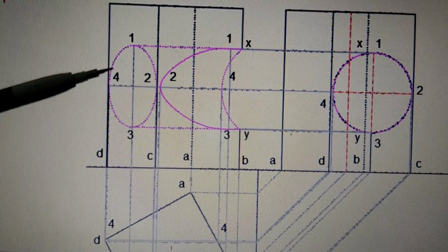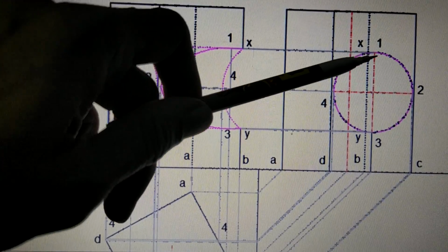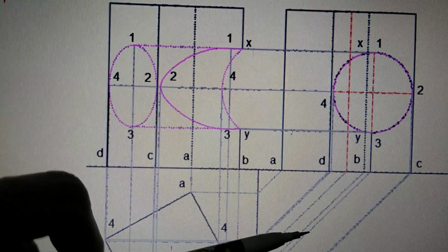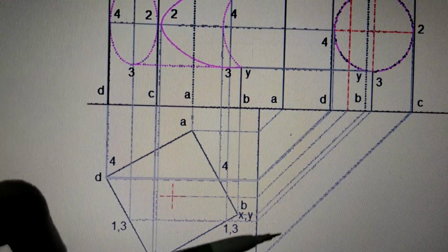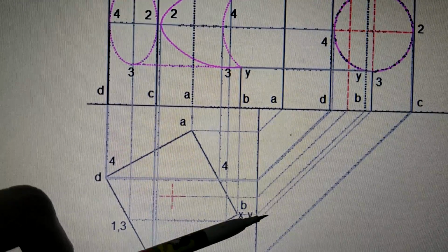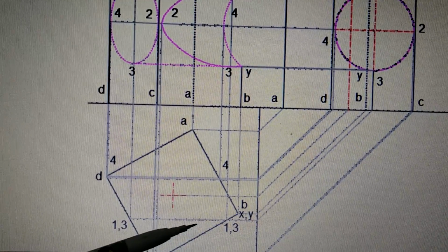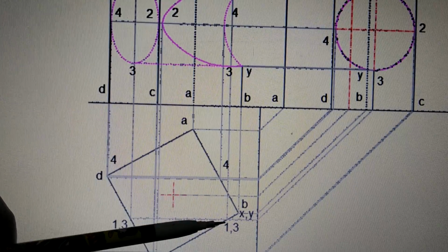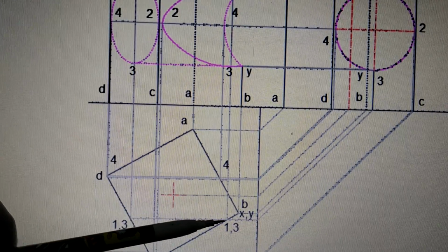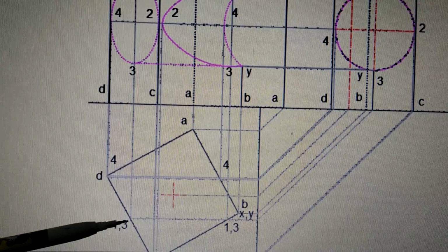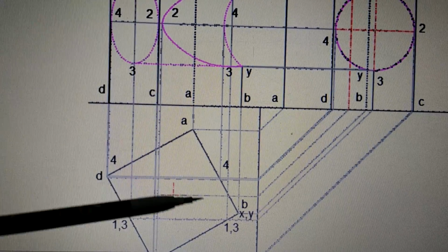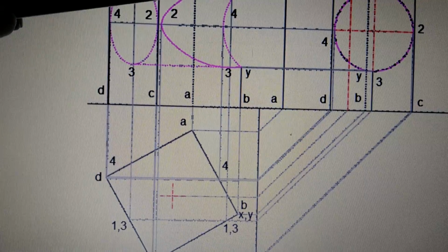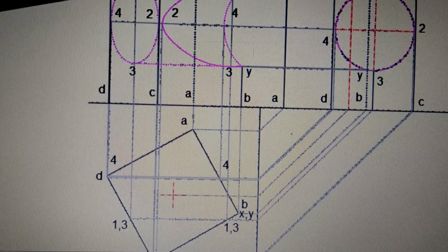Now how these points are plotted, we go one by one. So first is point number 1, which is on this generator. So we draw this generator in the top view. So you can see here, this is the generator coming here in the top view. So this line at 1 is intersecting the prism like this. So it will enter inside here and it will come out from here. So this is the position of 1 and this is the position of 1 on this line, and it is at this height. So point 1 is here, point 1 is here on the two sides.